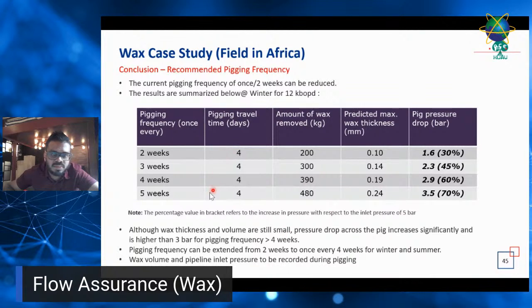Based on this analysis, we recommended and proposed to extend their pigging frequency from 2 weeks to 4 weeks, to reduce the pigging induced slugging issue.